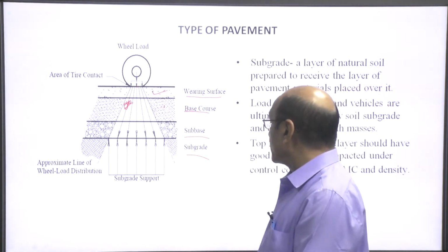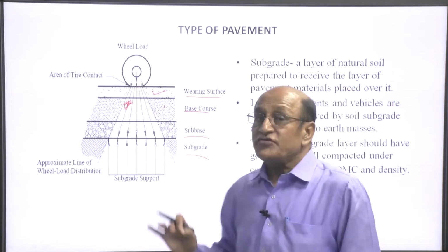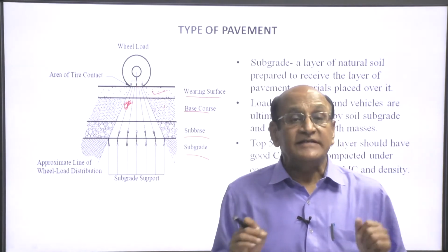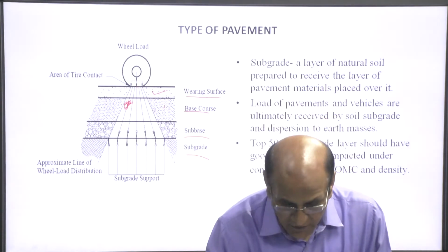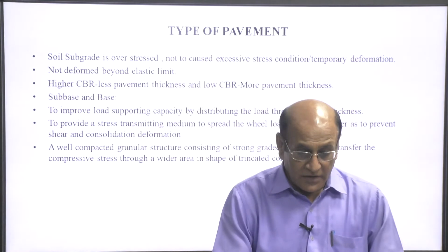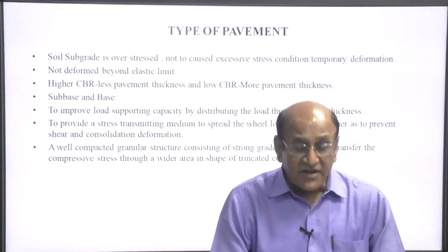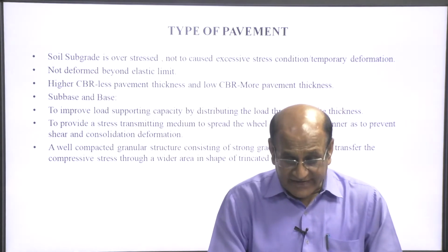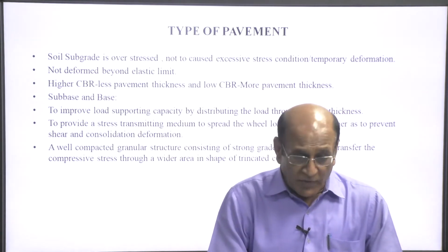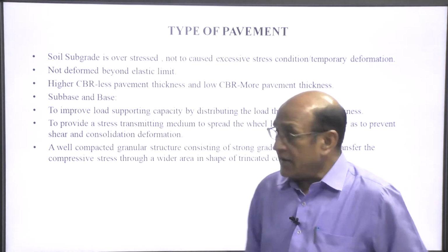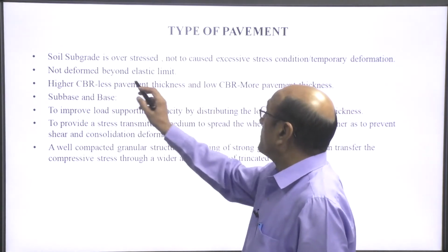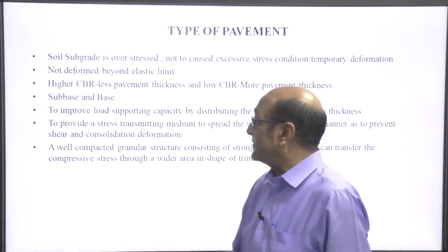This 50 centimeter thick layer is called subgrade. The soil subgrade should not be overstressed to cause excessive stress or temporary deformation, and not deform beyond its elastic limit.